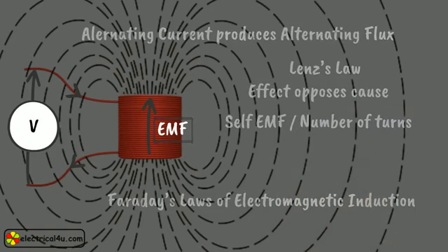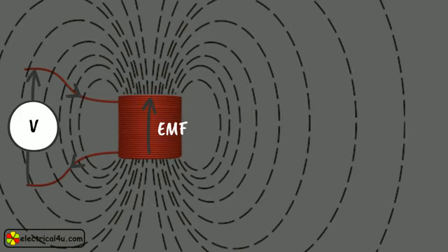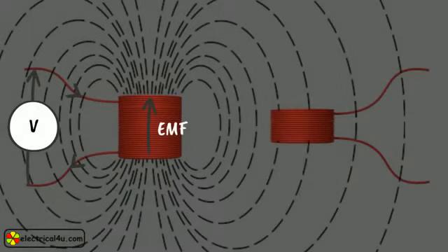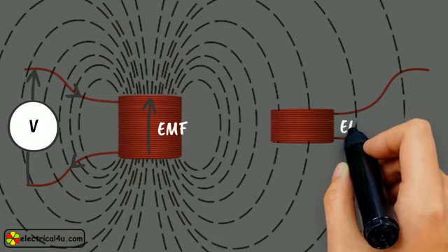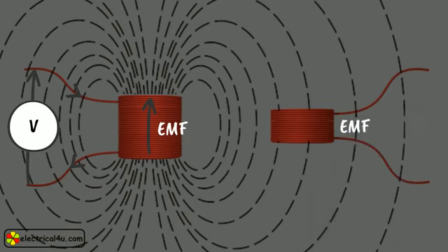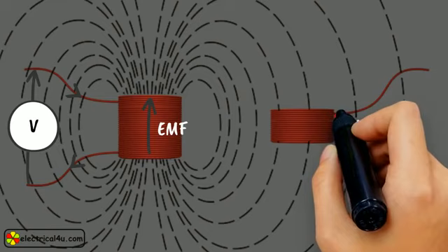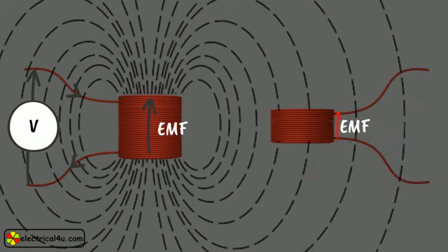We have said that there is another winding in the most basic transformer, but till now we have not discussed it. Now we come to the second winding. Suppose one separate winding is brought nearer to the first winding. Then this second winding gets linked with a portion of the varying flux of the first winding. Due to this varying flux linkage, there will also be an induced EMF across it. This induced EMF would be quite small, because the flux linkage is small.